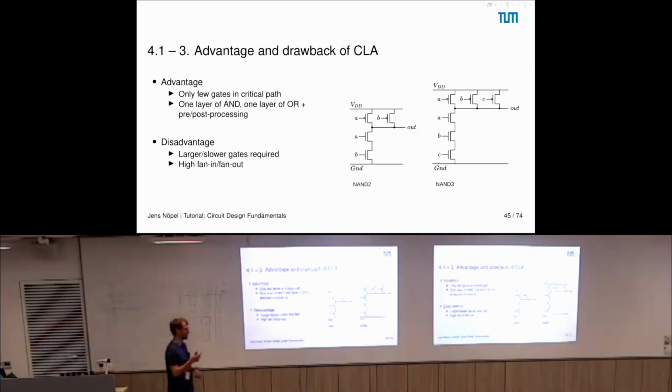And now the interesting part begins. So what you usually then do, if you create a NAND gate, a NAND gate looks like this, right? So the NMOS are in series and the PMOS are in parallel. So this is how you usually design CMOS gates. So the design of CMOS gates is something you've heard before?